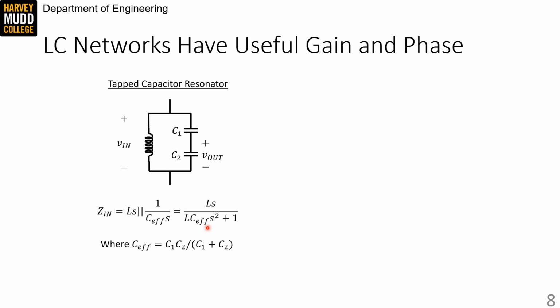So these funny behaviors are because we haven't included any resistors in our circuit, which means that this is kind of an idealized system that will transfer infinitely quickly in response to frequency changes. So those behaviors are distracting, but they paint the broad strokes of how a parallel LC resonator works. At low frequencies it looks purely inductive, because the caps are high impedance, and so we get an overall positive and purely imaginary impedance, j omega L on top.